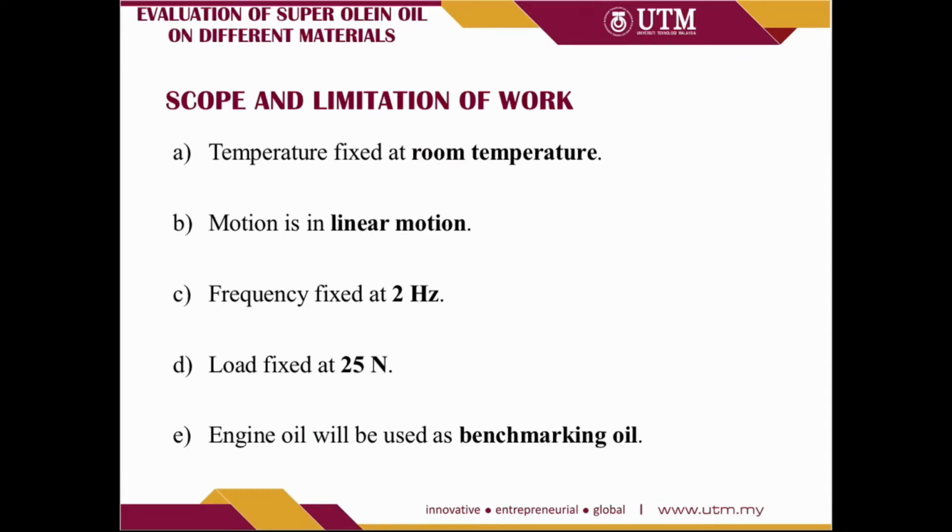However, these are the scopes and limitations of my project, in which the test parameters that need to be taken into consideration are: the temperature must be fixed at room temperature, the motion is linear, the frequency is fixed at 2 Hz, and the load is also fixed at 25 Newton, and the engine oil will be used as a benchmarking oil.